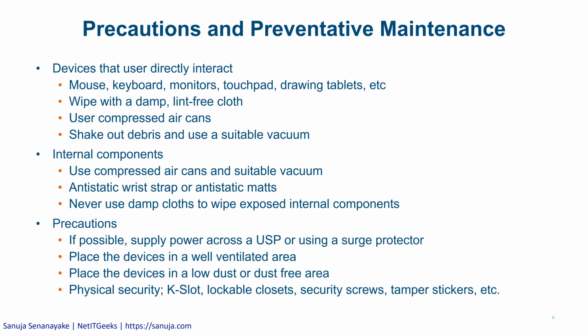So when you're using compressed air cans, it's okay most likely, because it's going to be really hard to cause damage, unless you are holding the compressed air can in the same place and pressing it down until water droplets form on that one part of your computer. So make sure that even with compressed air cans, you go back and forth and not just stay in one place. It's a little bit harder to cause damage with a compressed air can, but with an incorrect vacuum you can seriously damage your components.